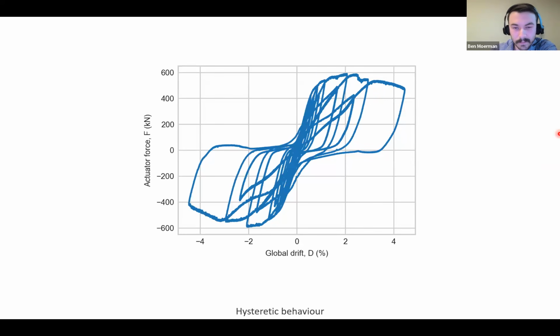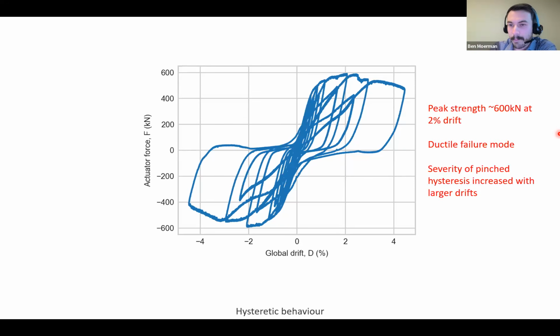So overall, I feel the system was reasonably stiff. It's usually something timber systems struggle with, just stiffness, especially at the SLS level. And in this coupled wall system, we have the link beams tying the piers together, stiffening everything up, and overall it performed reasonably well. We can see we did get some pinching, just like the cantilever walls, but it wasn't as severe, and especially if you ignore that last cycle all the way to ultimate, the pinching wasn't too severe.